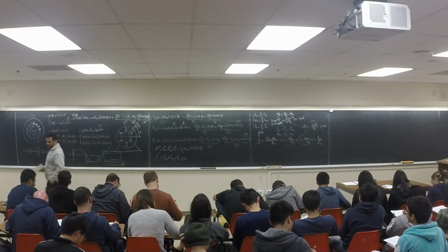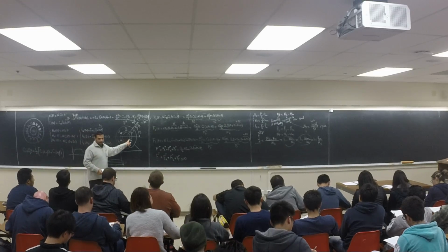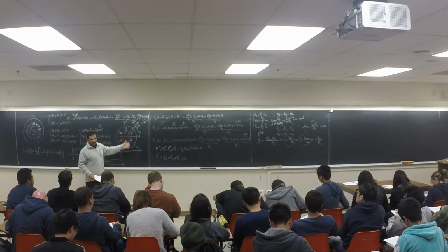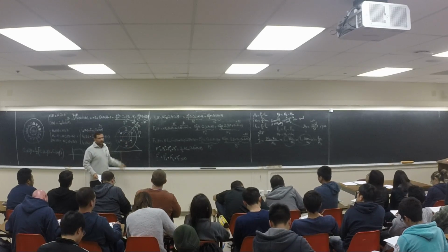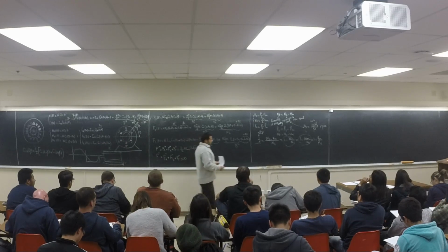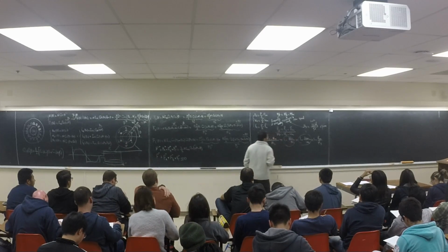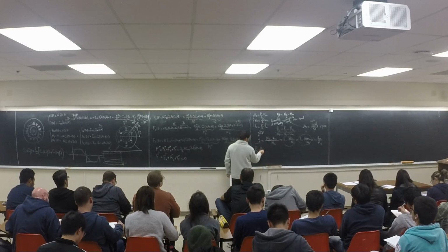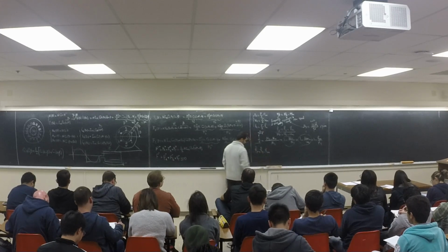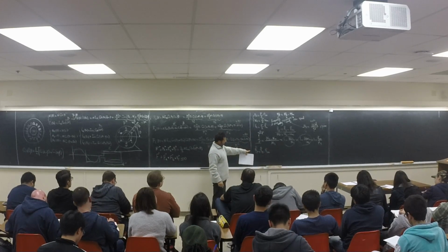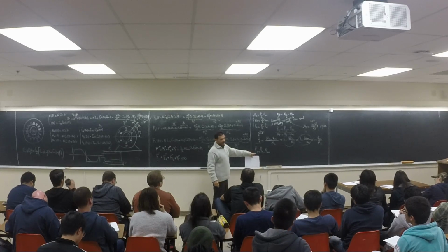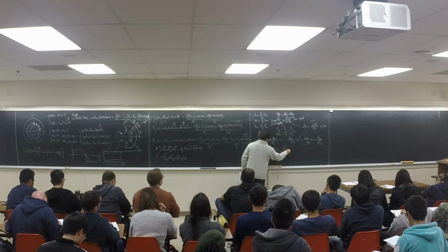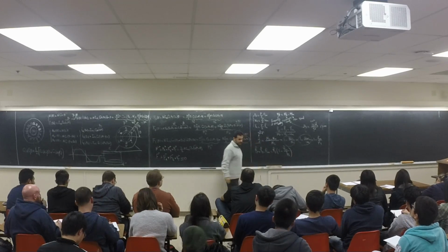Now let's find out what's the frequency in the rotor winding. What kind of frequency are we going to see here? I have Fs here, and this motor is rotating at omega M, or Nm, or Fm. Let's see what's the frequency here. We said the frequency in the rotor winding, Fr, is Fs minus Fm, right? Let's factor out Fs. It's going to be Fs times (1 minus Fm over Fs), right?